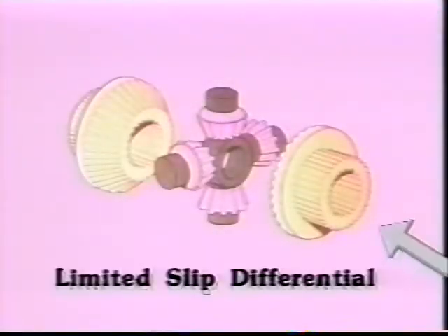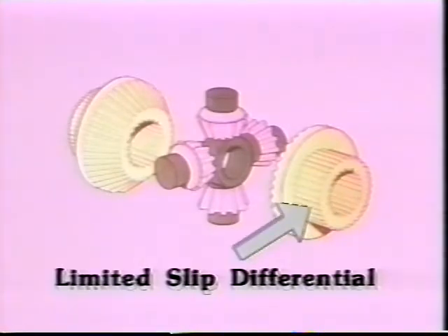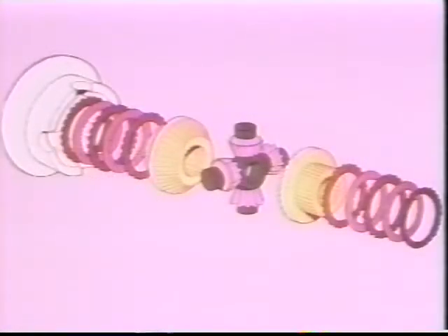The limited slip differential contains side gears that are splined on the inner diameter with teeth on the outer diameter. The differential case halves include internally cast lugs which hold the outer clutch plate stationary. The side gears are splined on the outer diameter carrying the inner clutch plates. With the case halves bolted together, the clutch plates are pressed against each other.